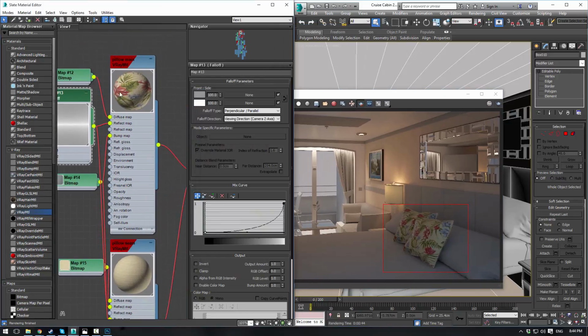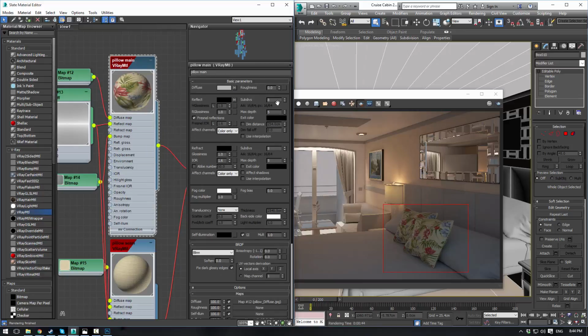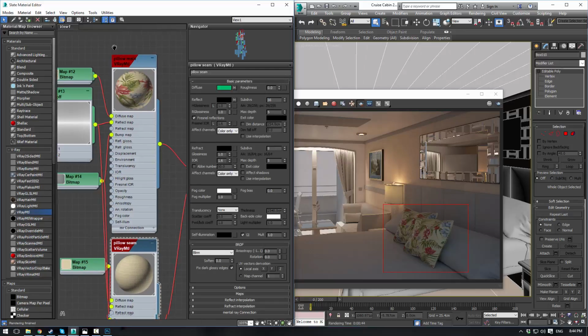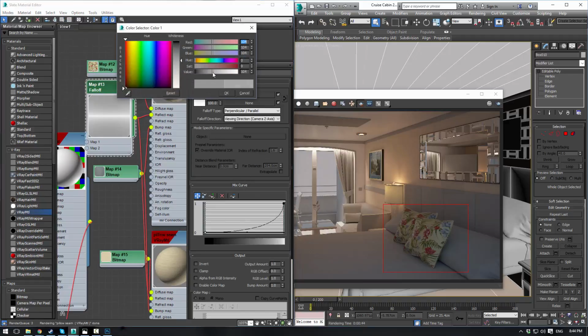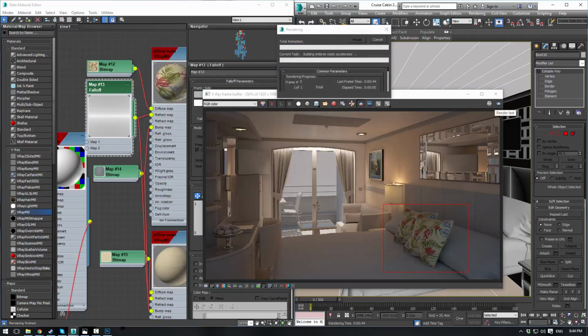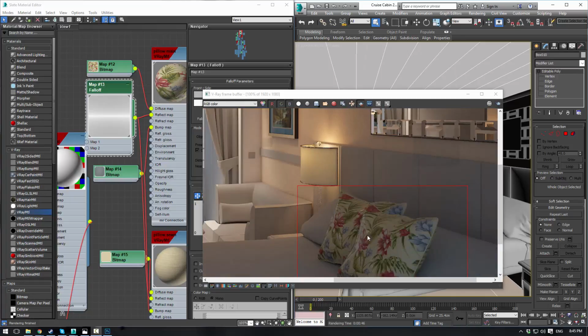Now let's also go to our main material here and change the subdivisions here to 16 on the reflect, as well as 16 over here, and then let's maybe get a bit lighter. Okay, and let's re-render it one more time. Alright, here we go. So we have these interesting sort of things here. I'm not sure what they're coming from. I think it's almost like specularity in there.